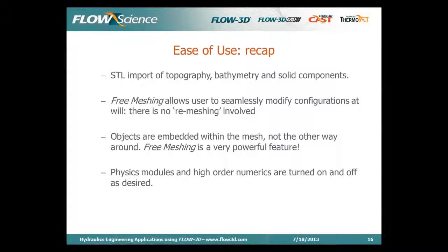Okay, so recap. It's ease of use, I guess, is the take-home message. STL import of topography, bathymetry, and solid components. Free meshing allows users to seamlessly modify configurations at will. There's no remeshing involved. Objects are embedded within the mesh, and the physics modules and higher order numerics are just basically turned on and off as desired.